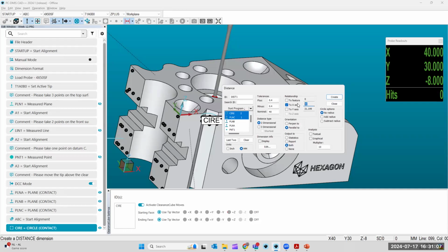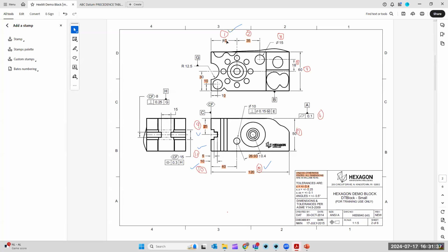If you see this and it makes sense to the drawing, that's what you need to look for. You can also often change it to 3-dimensional and it recognizes that I'm actually looking to do it like this, and I'm doing this distance, not this distance. So you play with it until you identify the nominal you're looking for correctly. Obviously, we're looking for 40 millimeters because our drawing's nominal is 40 millimeters. The CAD model and the drawing should have the same nominal. The part won't have the same actual value, but it has the same nominal, meaning the designed value.